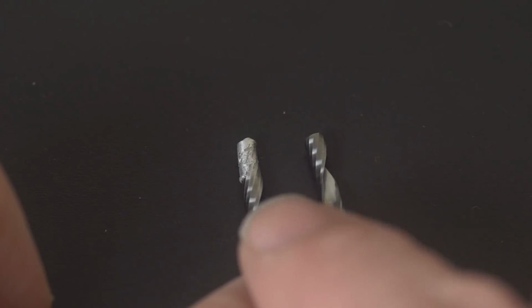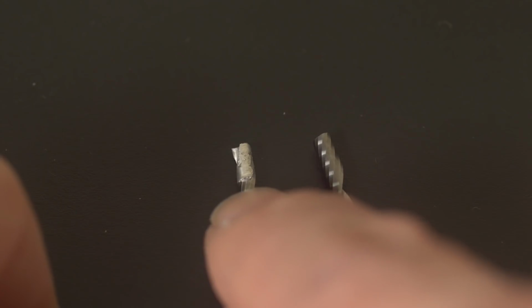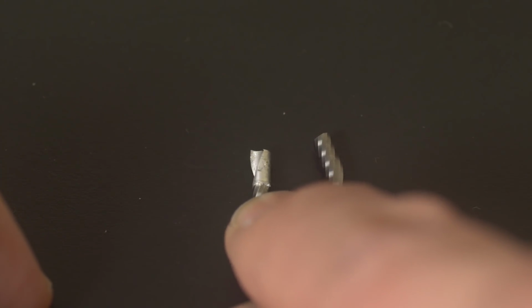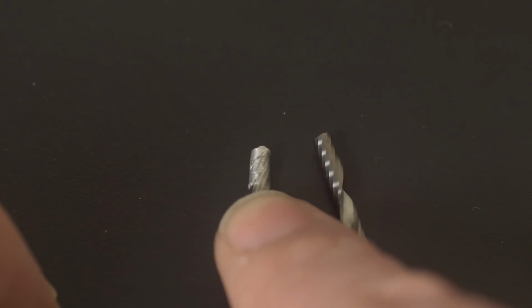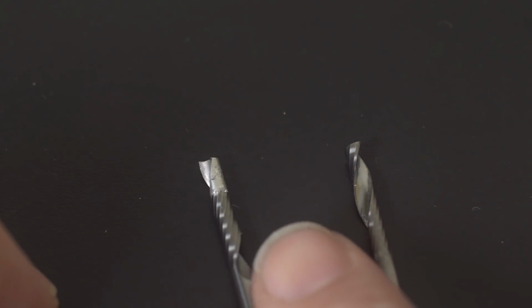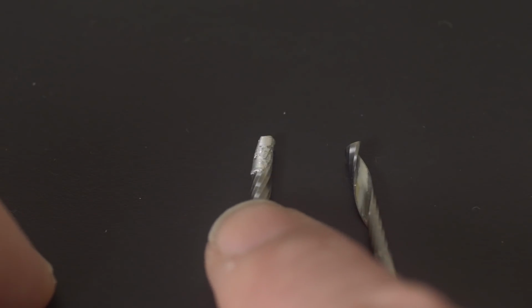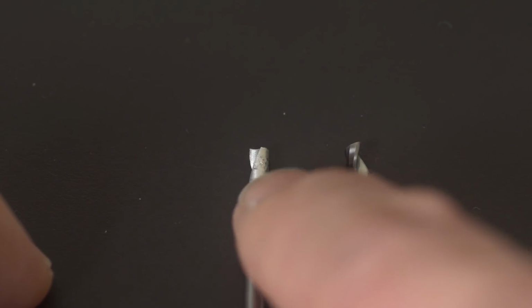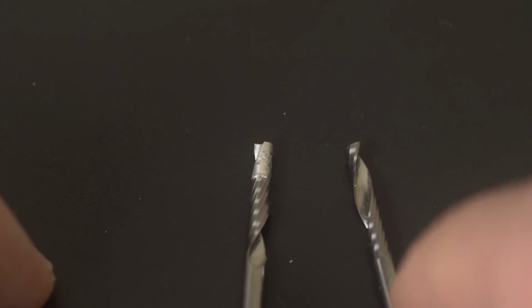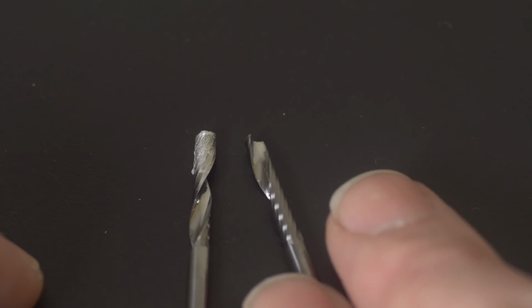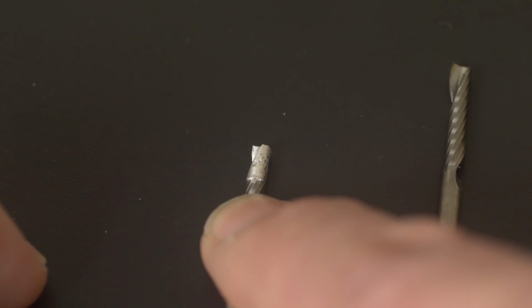Here on the left, see this bit that looks like the dog's breakfast, as they say? So that's a bunch of aluminum that has friction welded itself to the bit. Now the cutting edge looks okay, but it's not doing a good enough job clearing the chips out of the slot, and so there's just a bunch of loose chips in there that have mashed themselves and bonded with that bit. So this on the right is what one of these bits is supposed to look like. This bit will never be the same.